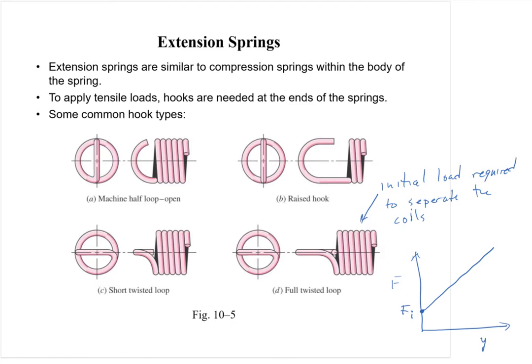That's something I noticed from a student experiment. I had a student in my vibrations class build a little vibration mass spring type of test platform, and she was getting weird answers compared to her simulation, and we determined that the extension spring she was using started with fully solid length collapsed coils, and that there was actually a small amount of force required to even get the coils to separate.